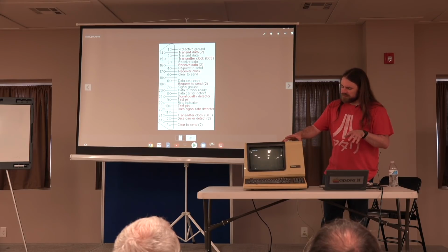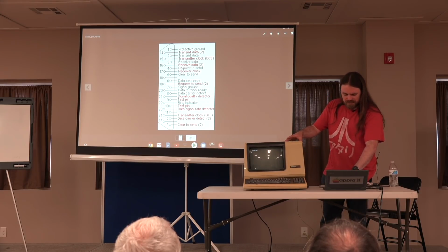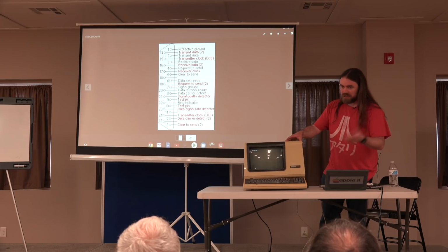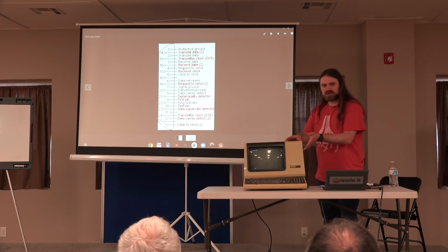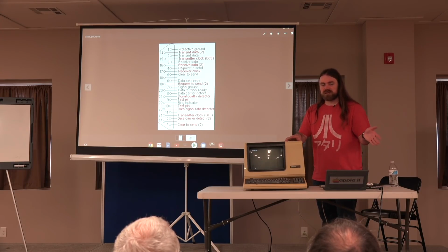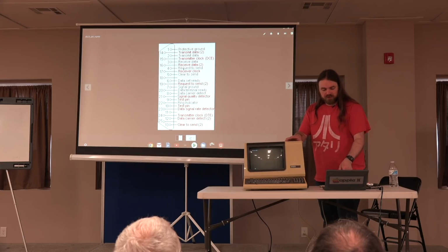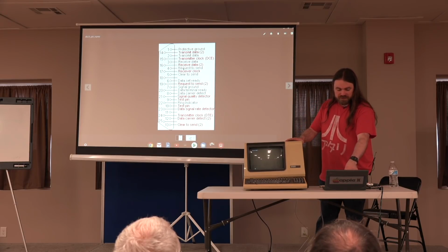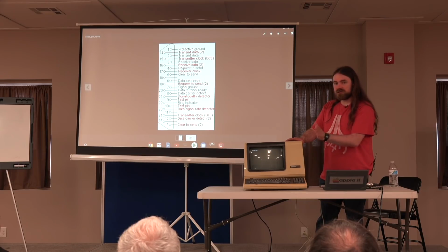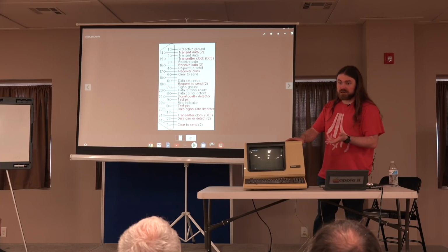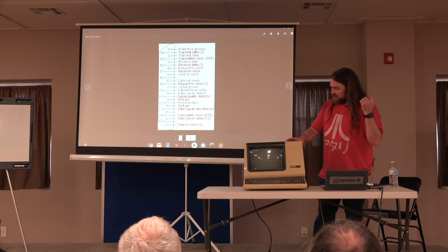So the serial data is being sent by the computer, but the terminal can only process it so fast, the computer can only process it so fast, so they can kind of start to overrun. So then there's 2 methods of flow control. There's hardware flow control, which actually uses these extra control lines to stop the transmission of data, resume the transmission of data, or it's done inline with control characters.